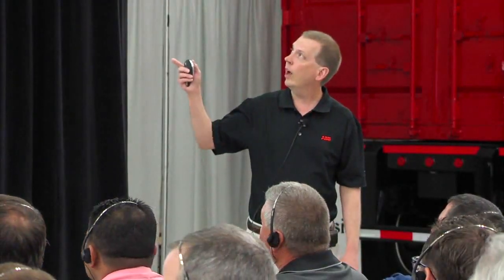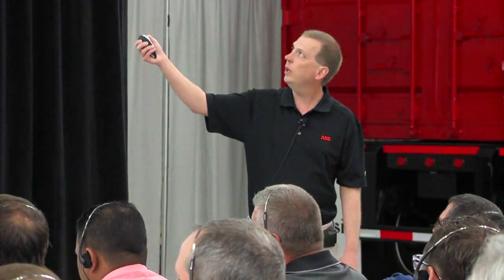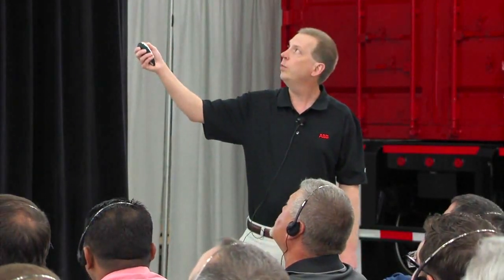I do it by preset speeds. So I go into my drive and I say, okay, constant speed 1, that's going to be 900 RPMs. Constant speed 2 is going to be 1,000 RPM. Constant speed 3 is going to be 1,500 RPM. And I program those in there.